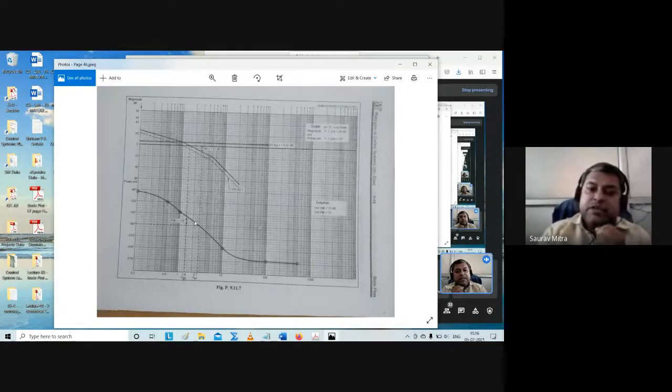So that means gain is stable, that is less than 0, and phase is also stable, that is greater than minus 180. So what is the sweet spot? This system we have designed so that we can operate it stably in between 1.4 to 2.7 radian per second. So this is the significance of gain margin, phase margin, omega GC, omega PC, and system stability.